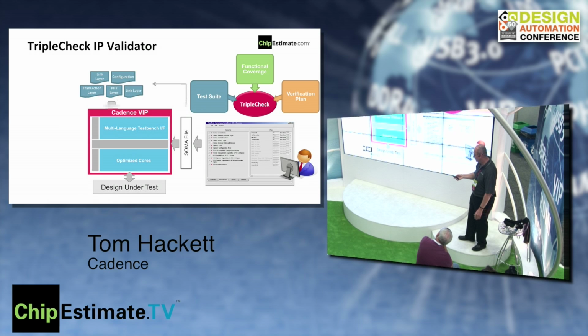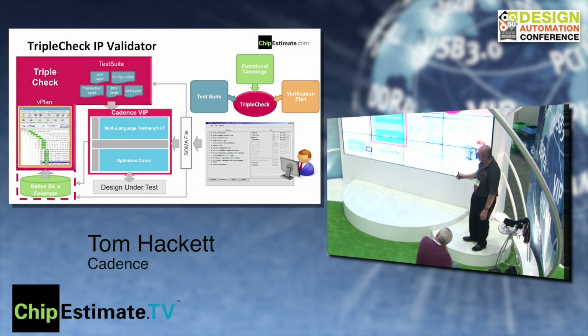Okay, so then you run your simulation, and it outputs a coverage database. And this coverage database is in native SystemVerilog and the e language, and that will allow you to import that into any simulation environment to go and debug it. So that makes it independent of the simulator in terms of debugging. Use any one you want. But if you're using the Cadence simulator, it will pull that into an interactive verification plan. We call it a vPlan.